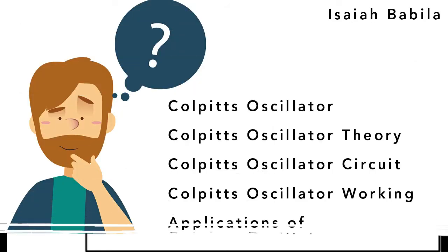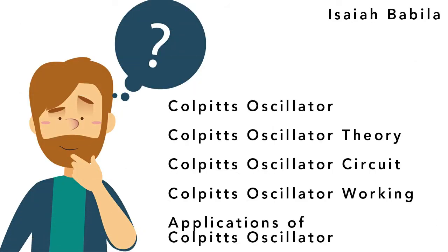The capacitors C1 and C2 form a potential divider, and this tapped capacitance in the tank circuit is used as the source for feedback. This setup provides better frequency stability compared to the Hartley oscillator, in which tapped inductance is used for the feedback setup.